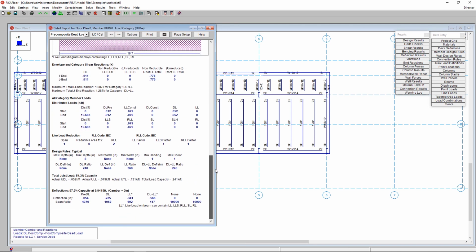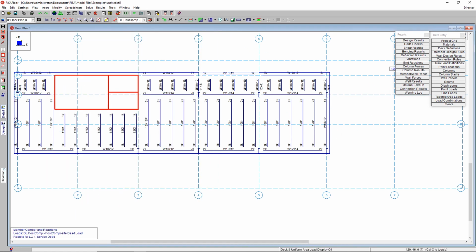joist table. So it tries to figure out what the joist capacity is, and right now I'm using a 12K1, so we see the capacity of that, and we're going to fit that inside of that total capacity, and then we try to back into this calculation of the deflection and find the most optimal joist for you in those situations. So you've got the joists running across there, and you're sizing them as you need, as well as your wide flange results right there too.